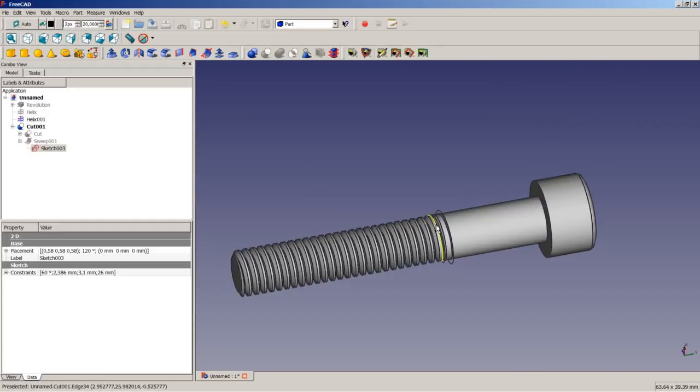Speaking of mechanical engineering, not in case of screws, but mostly in cases where you will cut the thread yourself to mechanical parts, there is also the option to have a groove at the end of the thread. A groove with an inner diameter of less than the inner diameter of the thread, so that the tool used to machine the thread will end up in empty space at the end of the thread.